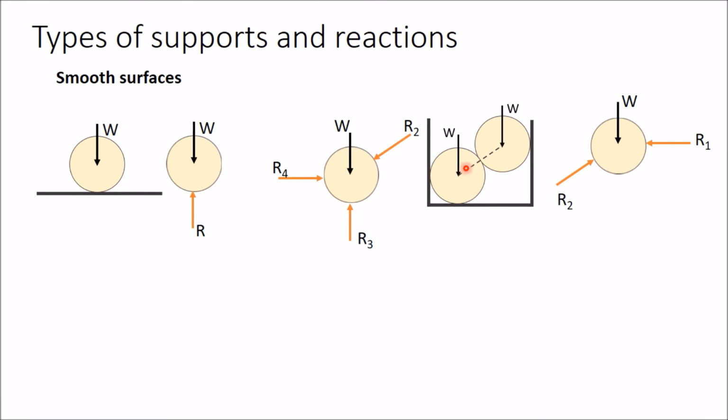Now if you want to draw the free body diagram of both spheres together, draw these spheres. Since these two are joined together, they do not get separated, and therefore there will be no force at the contact point. First you show the weight of these spheres in the vertical downward direction. Now at this contact point we have removed, and the same force R1 you have to show, same name and same direction.